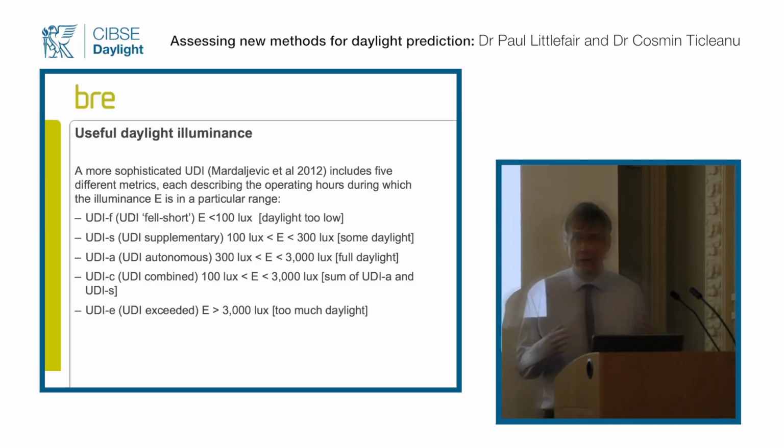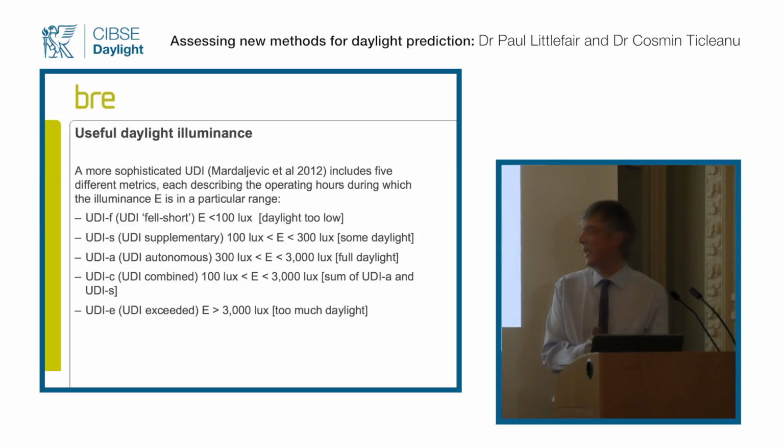Well, again, I agree with the last thing, but I think I understand the point you're making. If we just took 3,000 lux, the UDI reacts to that. If we're using 3,000 lux, it doesn't actually matter whether it's diffuse, because perhaps you're really close to a window on a bright day, or whether it's 3,000 lux because the sun's shining on it.